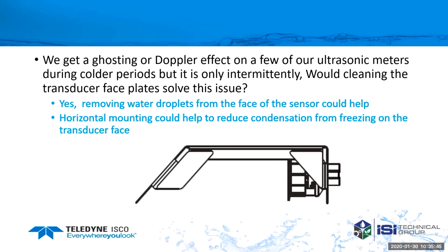All right, now that it's colder out, I've had several questions coming in about cold weather, and this person is having problems with getting ghosting with their ultrasonic sensor when it's cold out. They were asking about cleaning the face of it. So yes, cleaning the water droplets off the face of the sensor could help. If it's mounted in a vertical orientation with colder weather, sometimes we get steam coming up.